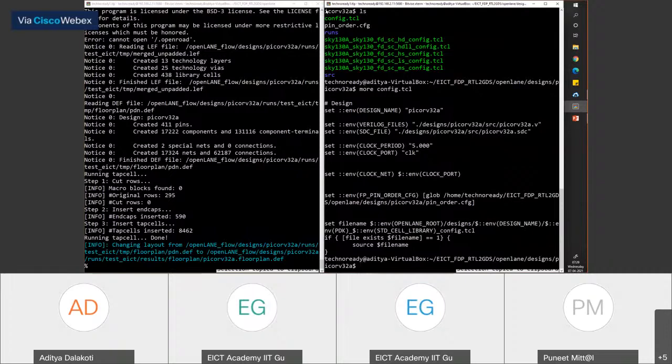George, OpenLane also runs synthesis. The reason we did not run synthesis directly using OpenLane initially is because it limits the freedom to explore the design, because of the way it is structured in a tool environment. With directly running Yosys, you had a lot of freedom and you could understand different stages of synthesis, and it lets you better appreciate what happens during synthesis and how you use it.